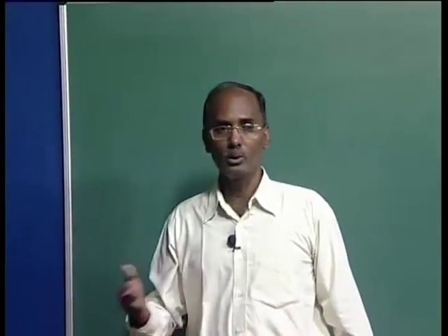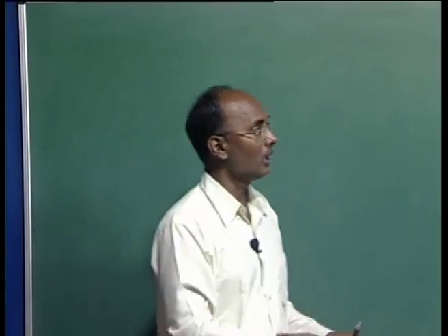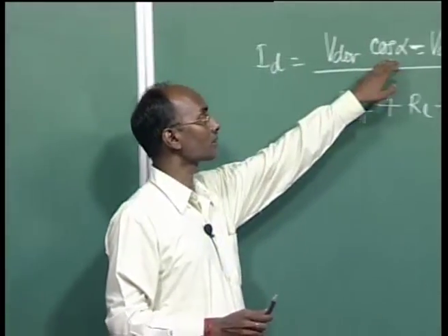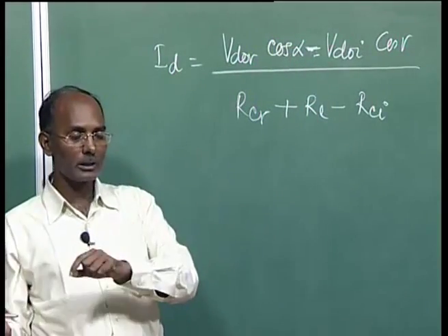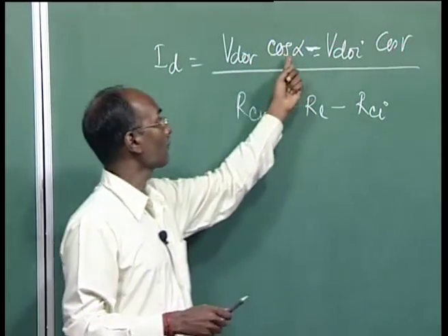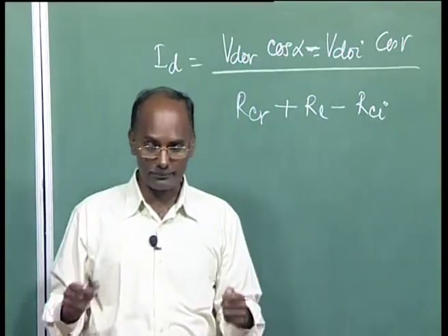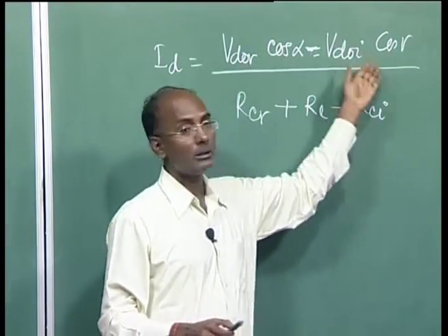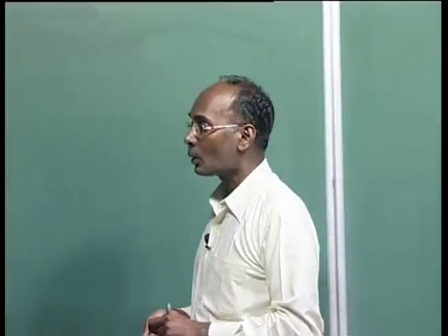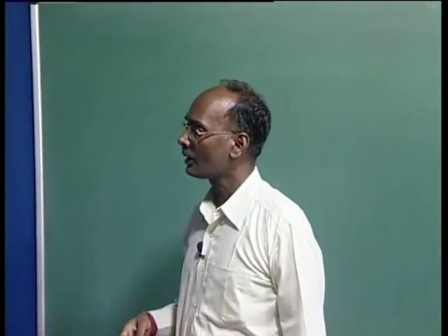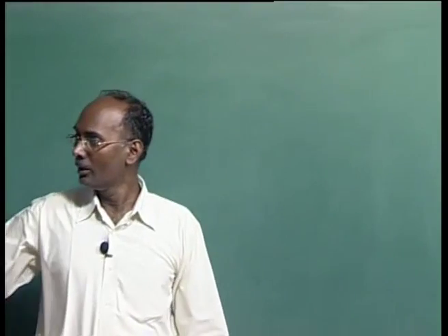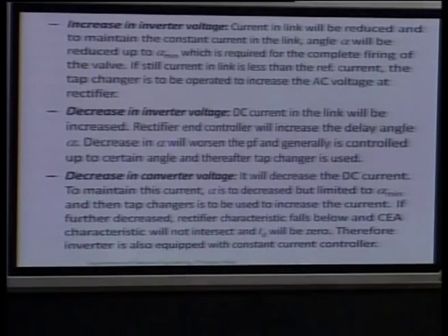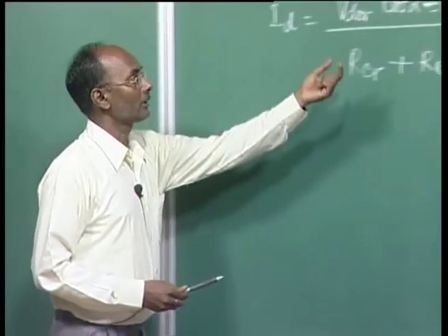So we have to operate our OLTC once we have exercised all this firing, that's the valve control. The valve control means either inverter side or rectifier side. This alpha and gamma we have to exercise first, then we have to go for the rectifier and inverter OLTC transformer. The scenario becomes very bad when there is a decrease in this voltage.